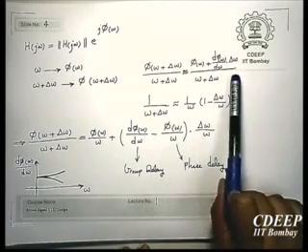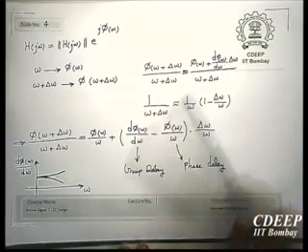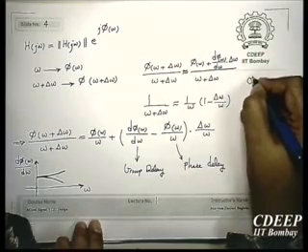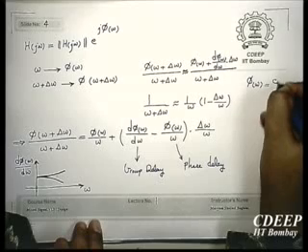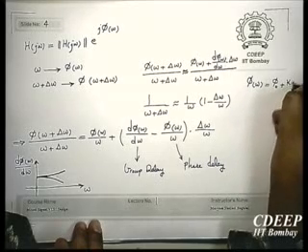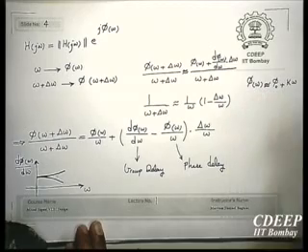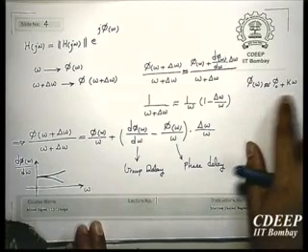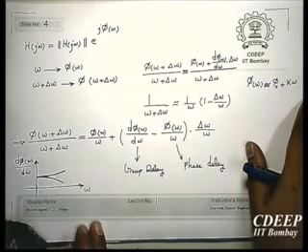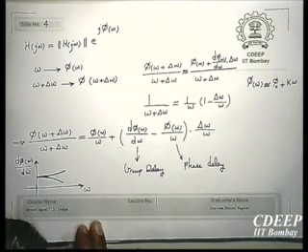If you have made a filter in which you cannot ignore the second order, what does it mean? It means that you can write phi omega in the form of phi 0 plus a constant times omega. If you have made a filter in which you can write this relation, then you can write this. But if you have made a filter which has more than these terms, second order terms, then it's not a good linear phase filter. And it depends, of course, on how much linearity you define. It defines how much you define your group delay as a function of omega.